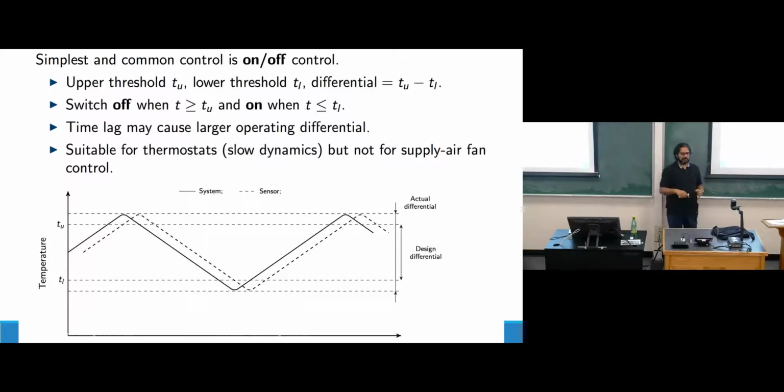The facilities managers aren't really tweaking the gains of PID controllers. They are just specifying, I want this band to be narrow or very large. The narrower it is, the more high fidelity temperature control you want for your zone. The larger this band is, the more flexibility you have in terms of how much deviation you can have from the reference. Okay? It's just sort of a moot point over there that we'll revisit.